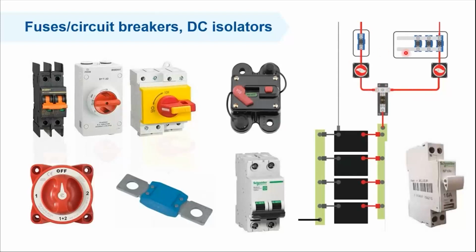What I normally prefer in design when it comes to sizing is that I might use a cable with higher capacity. As I told you, if I have options for thicker cables, it's always good to use them. But I strictly adjust the fuse current rating a little bit higher, maybe let's say 1.5 times the maximum current of my system.